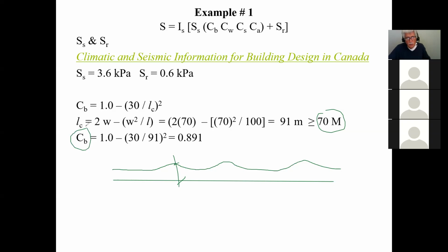When the roof is not that big, they found in theory that the snow load is fairly uniform. But when it gets big, like, if you ever go out and drive and look out on the field, you see little bumps that occur in the field. Those little bumps can actually occur up on a big roof, and to calculate how much more that bump is going to weigh on the roof, that's what the CB value is all about, okay?